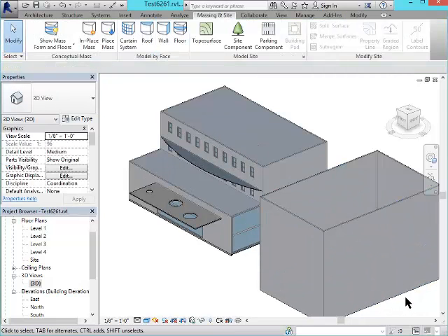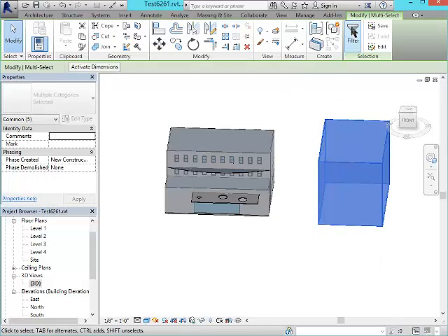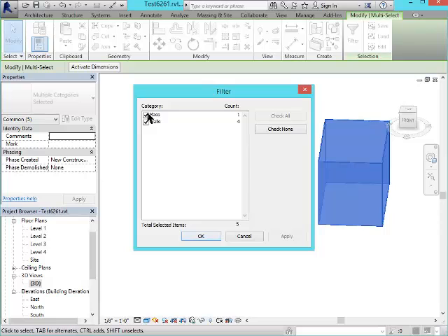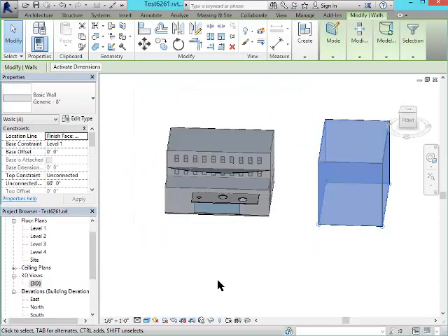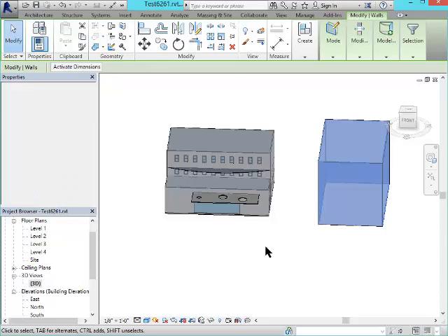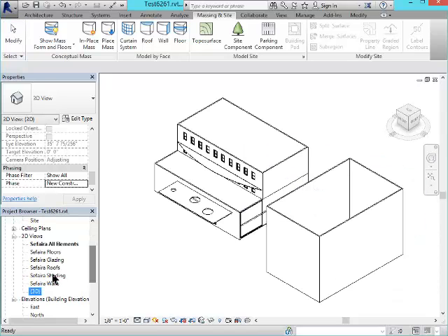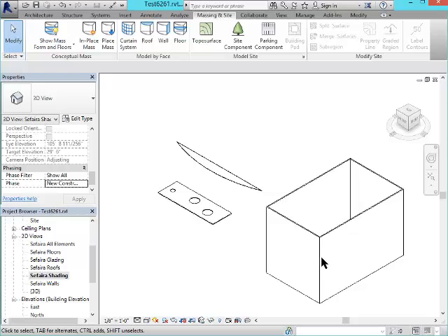And I want to select those elements, filter so I can just get the walls first, come down and uncheck Ignore and apply Shading. And now once again, if I generate my Sapphira views and I look at my shading elements, I can see that that adjacent building would be casting a shadow onto my building.